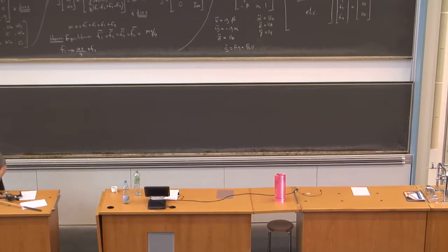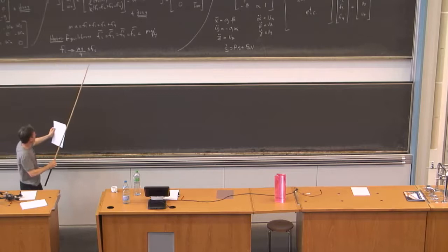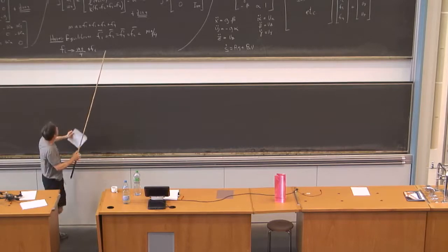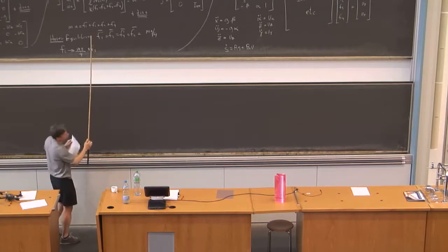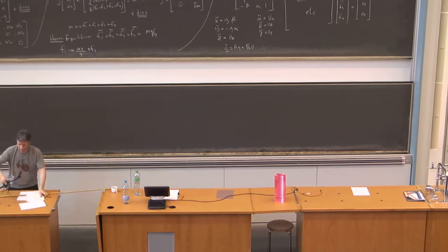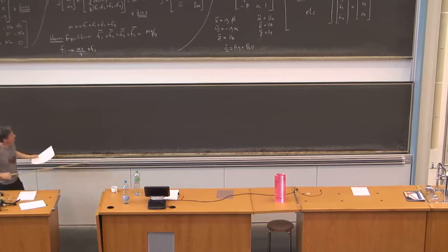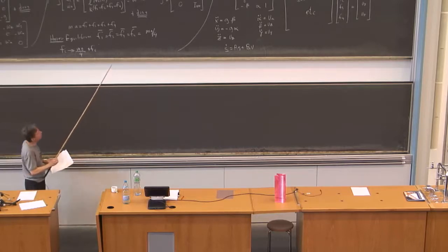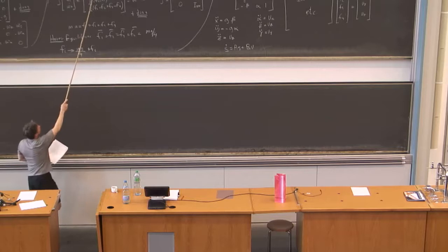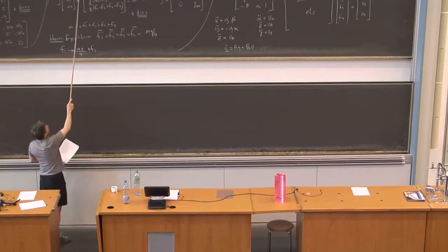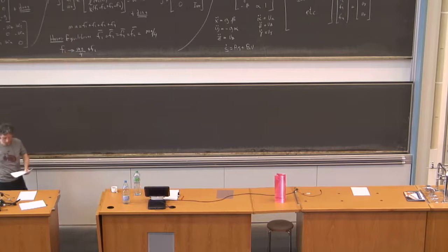So, second, then I'm going to assume, I'm going to set... which ones? I'm going to set F2 and F4 equal to 0, right? So basically, I can't produce thrust with these two propellers. So in these equations, I'm going to set F2 and F4 equal to 0. You're going to see that now I only have 2 inputs instead of 4. And you can immediately see that I'm going to lose direct control of this omega sub x.